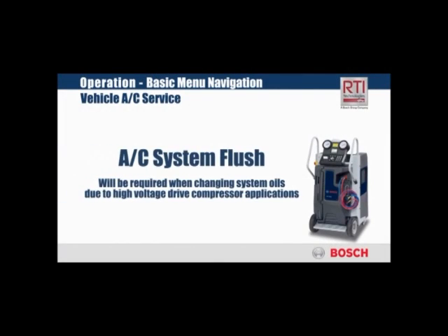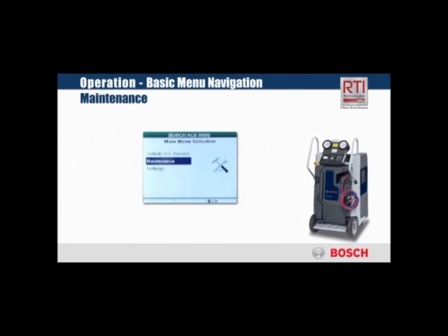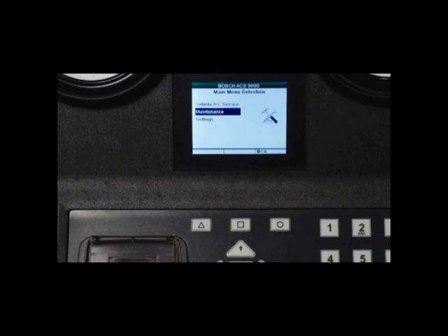AC system flush is required when changing oils between conventional and high voltage drive compressor systems. The hose drain function can be used for a manual hose evacuation process. Next is specific equipment maintenance functions. Go down to maintenance.